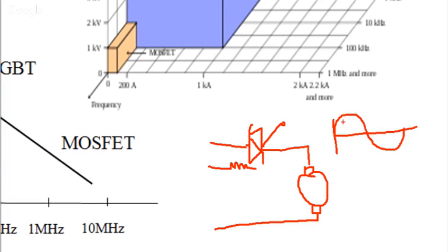You can reduce this voltage. AC voltage, positive and negative, you can do it. But what will happen? That power will drop there. Say we are giving 230 volts to this motor. Around 100 volts, you are dropping it here, and the remaining 130, you are giving it to the motor, so it runs at a particular speed. So this 100 volt, what is happening? It is dissipated as heat here. There is a power loss there.